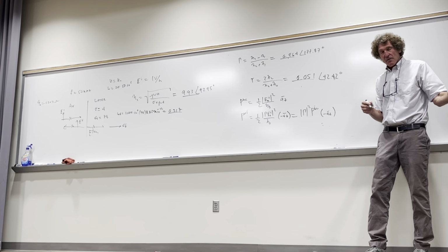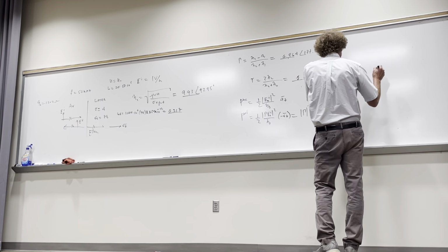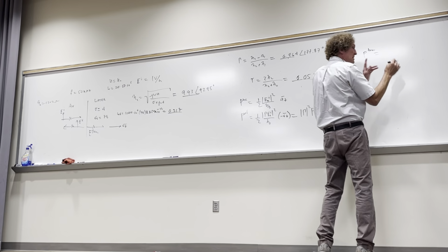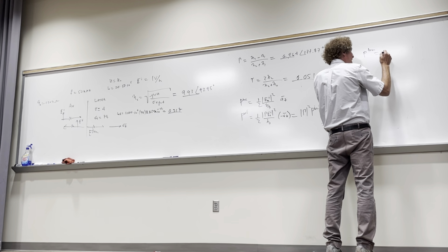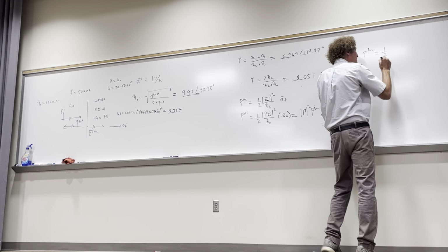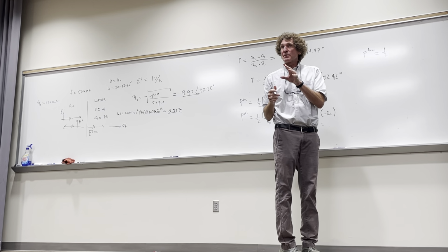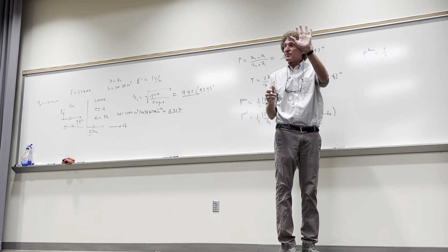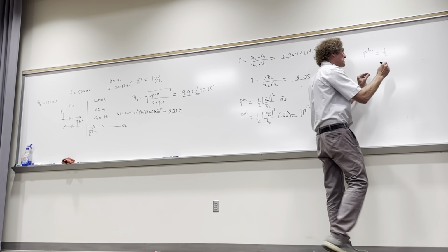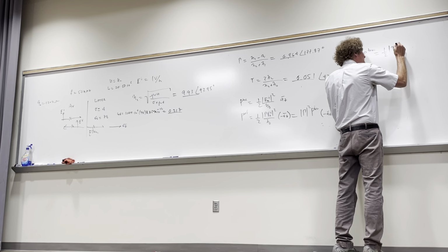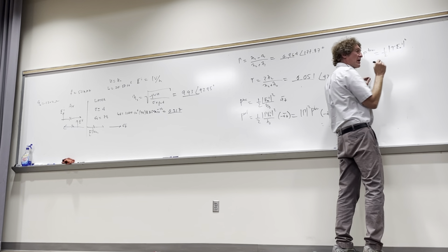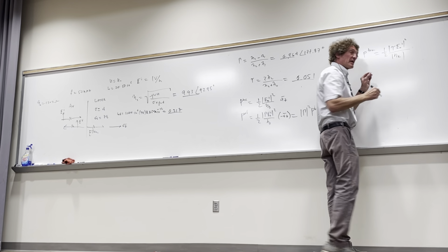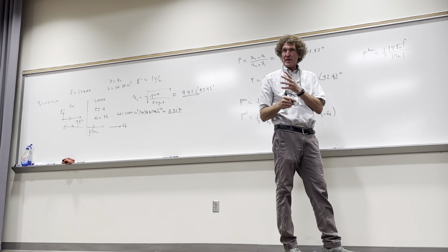Now for the transmitted power density, that's going to be a little different. For that one, I have to take, again, 1/2. That always is there. Then you've got to find the field transmitted. The field transmitted is going to be the transmission coefficient times E naught incident here, squared. Then it's divided not by eta 1, but by the magnitude of eta 2. This is the difference. Everybody follow me on that?